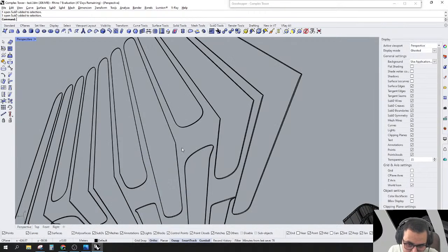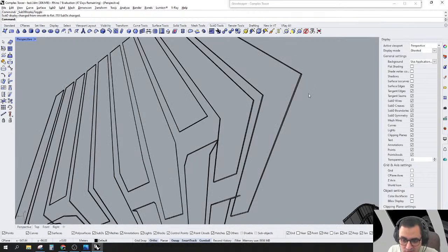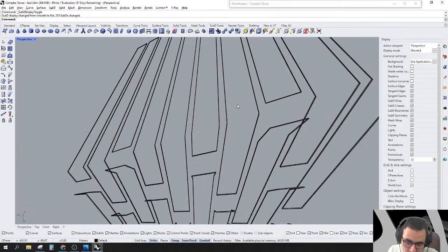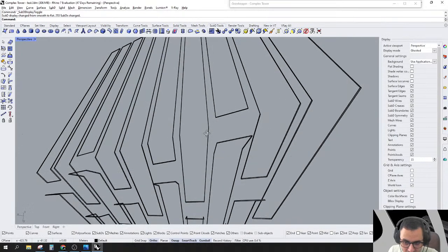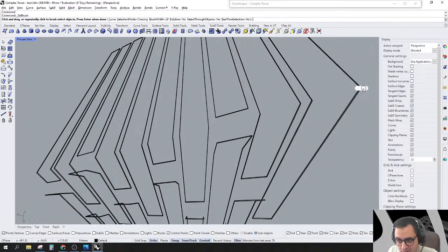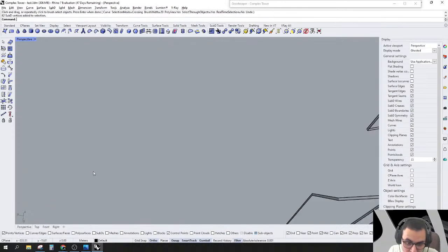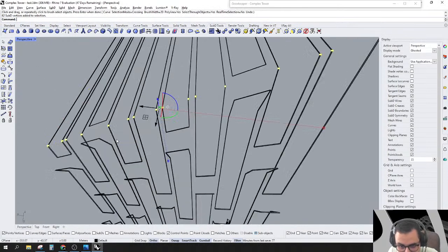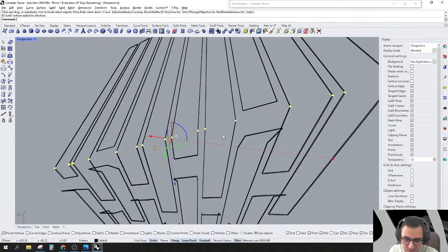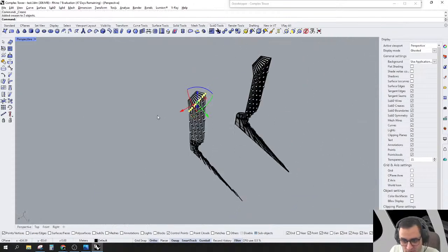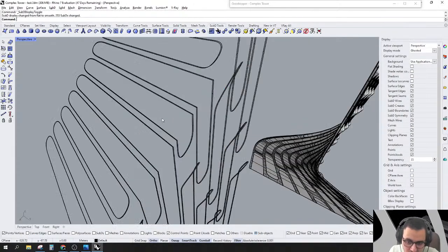the brush, select the vertices and go to the brush and select those until you've finished your line, and enter. Make sure that you are not selecting anything else than what you need, or simply remove it from your selection and go to crease, add crease, and now show me the final result.